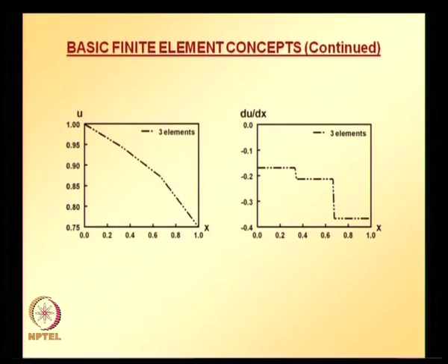So, what we did basically is that key concepts are introduced here: development of element equations and assembly of equations to form the global equation system. So, this is the new thing that you learned in this lecture, and it is necessary to develop element equations only once for a class of problem. To get a numerical solution, all that is needed is to substitute appropriate numerical constants. The concept of assembly of element equations to form global equations gives the finite element method a great deal of versatility. The assembly process is very mechanical: once you get the element equation, substituting the nodal coordinates and length of the element, all these things are mechanical, and this is ideally suited for computers. These concepts will prove even more valuable when dealing with more complex 2 and 3 dimensional problems.